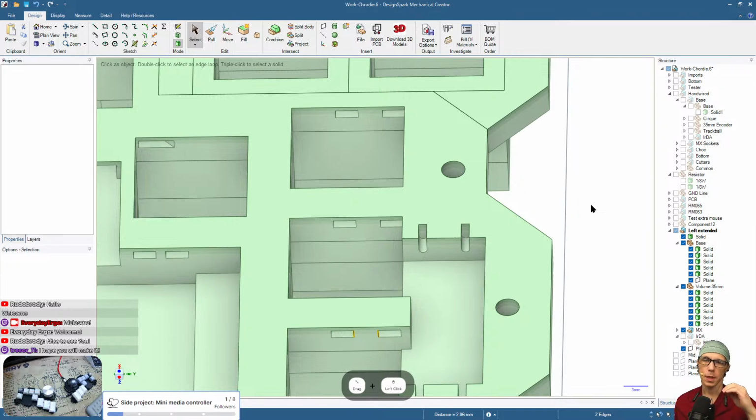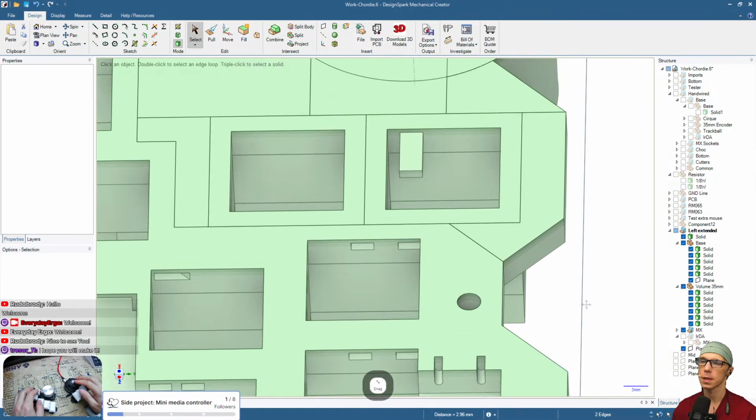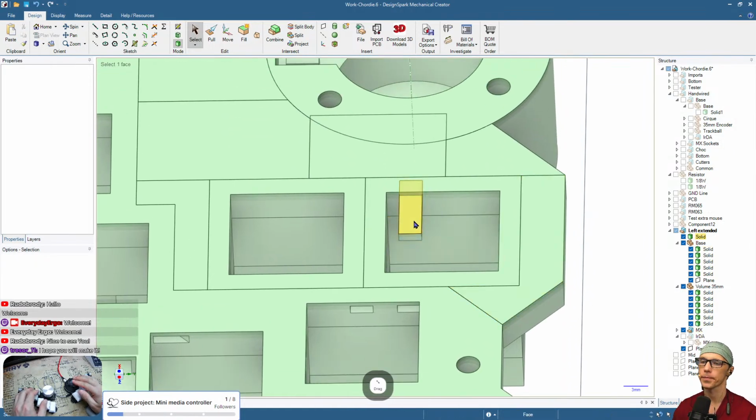I usually leave like, how to call it, the filament is 0.4, so usually I just leave like three times thickness of the filament, and usually I do 3 walls, so that will be 1 2 3, so it's 1.2. 3 times 0.4 is 1.2. So I think I will do it the same over here.